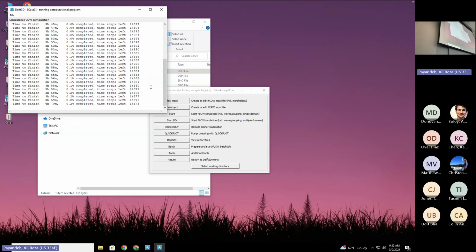Smaller time step, yes, we were using 4 minutes for case 1 and case 2, but here we are using 1 minute exactly. Okay, the transport equation, exactly, yeah. The main reason is that in case 1 and case 2, we were just solving shallow water equations. Here we are adding advection diffusion equations and so many other equations to the model. That's why it's taking longer.